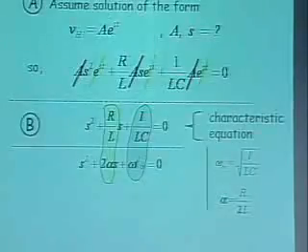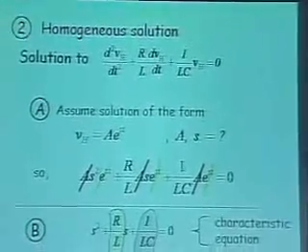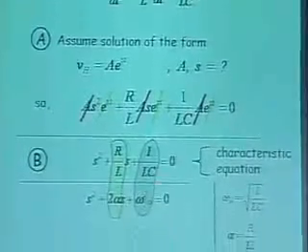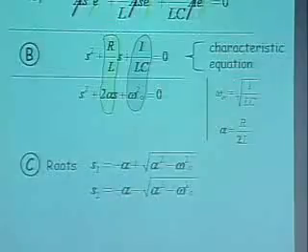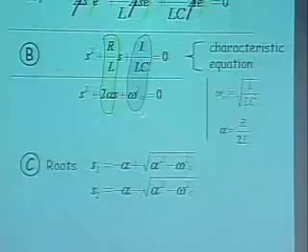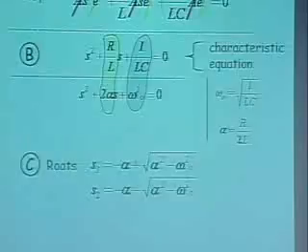Given this, I can now write down, so I'm simply replacing this as my characteristic equation and dealing with alphas and omegas. I'll give you a physical significance of alpha in a little bit. You remember the physical significance of omega naught. That was the oscillation frequency. In other words, given an inductor and capacitor, you put some charge on the capacitor, and you watch it, it will oscillate. Its oscillation frequency will be 1 by square root of LC. The magnitude of the initial conditions will determine how high the oscillations are, or what the phase is in terms of when it starts. But the frequency is going to be the same.